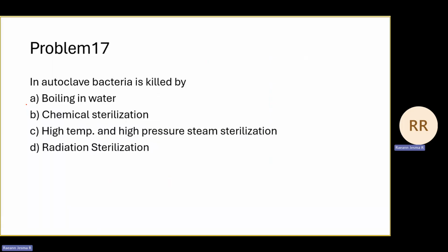So like we saw earlier, we heat water so that it gets evaporated into steam, and the temperature of the steam should be around 121 degrees centigrade. So we have this autoclave working at a higher pressure, which means that at higher pressure, the evaporation temperature also increases.